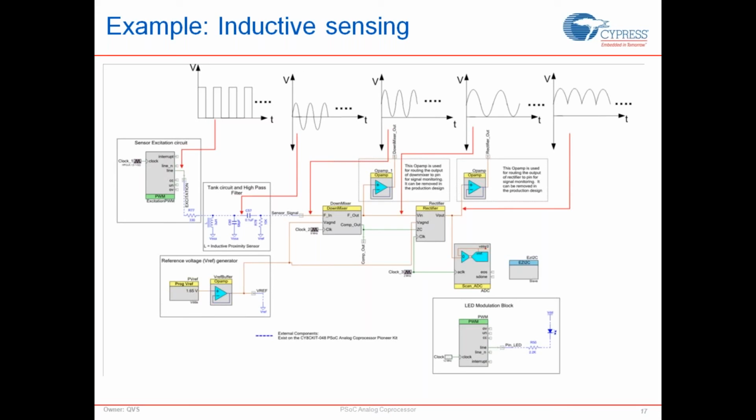You could also use this for limit switching, where you want to have a way of sensing the presence of a metal as a form of a limit switch for closed doors, locks, etc. So there are a lot of applications for inductive sensing, where you want to replace mechanical sensing mechanisms in industrial applications.